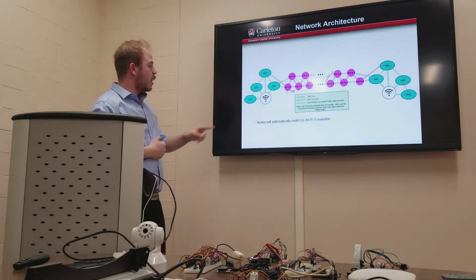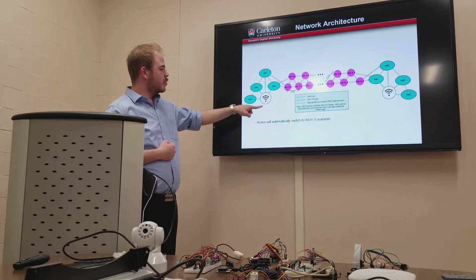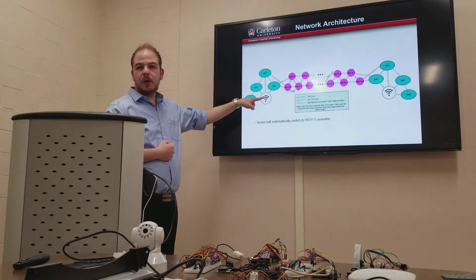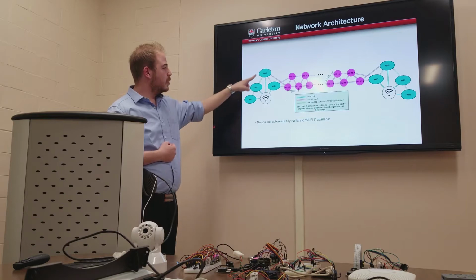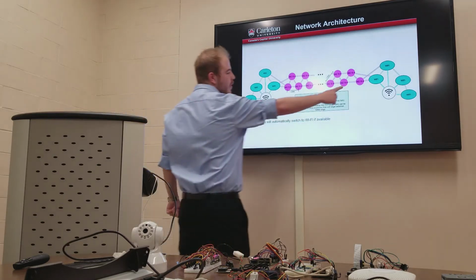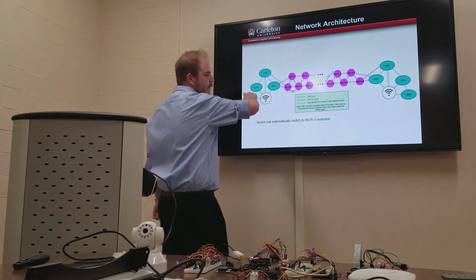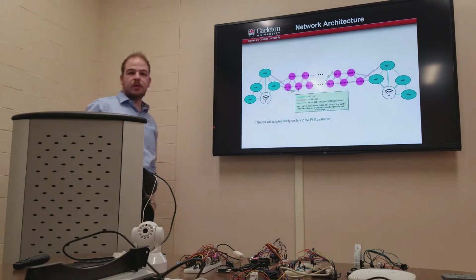What happens is our Wi-Fi nodes also can be Zigbee nodes. So in case this router goes down, all these nodes will turn into Zigbee nodes, and then one of the Wi-Fi nodes here will pick up all the data for these guys and send it to the server.